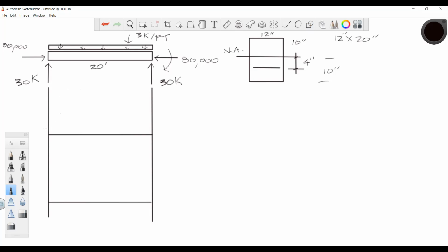What's the amount of shear on the left side? It's coming up at 30 kips, right? Yeah. What's happening as we step across that beam? It's going down. And it's going to go down at what rate? At a rate of 30, or 3 times 20. So that's going to give us a negative 60.